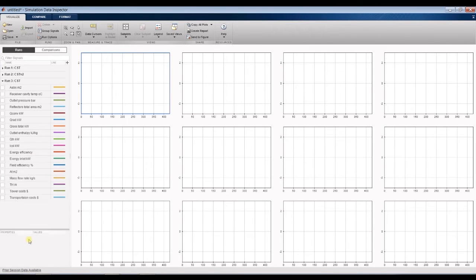What is going on? This is absorber area fluctuating according to your changes, and if you make another run, you will see the new data. Increasing the solar radiation is quite useful to your system because it will reduce the absorber area. Also, increasing inlet field temperature will reduce the solar field area, and this is the effect of outlet temperature, increasing and decreasing.